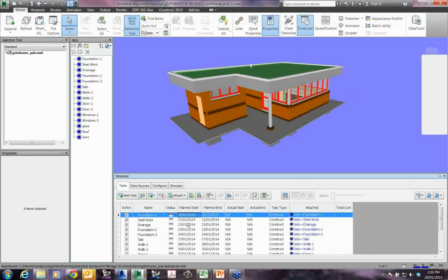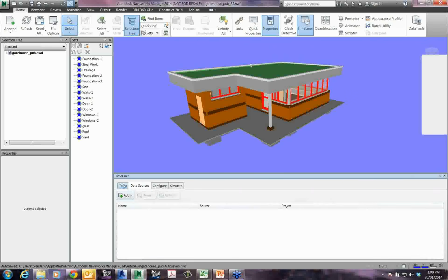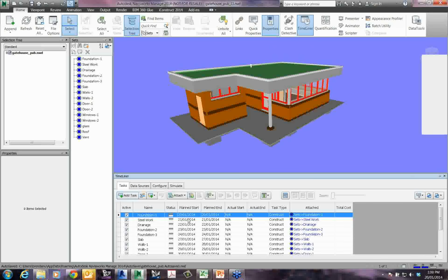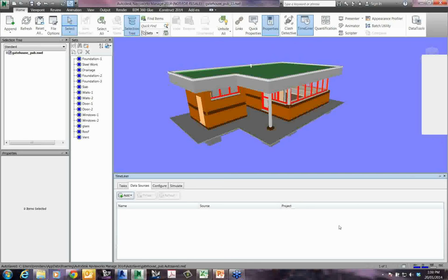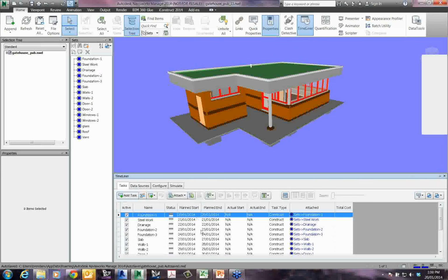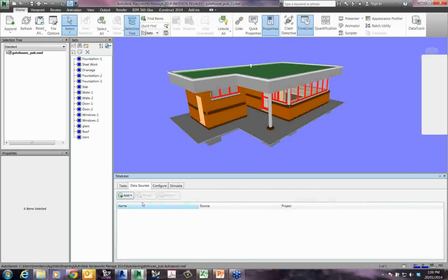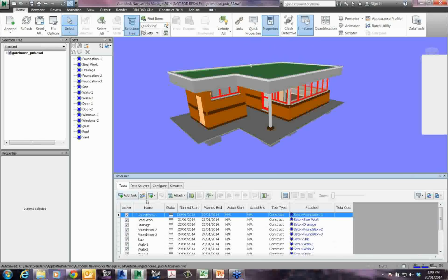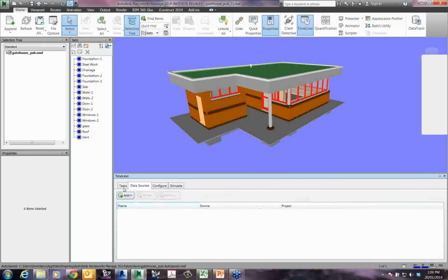Yeah, it's probably a good thing to note there as well, with updating the fields here. If you were doing this in the way that we showed at the beginning, by attaching a link to an external database, once you've built the task hierarchy from that link, from that external file, you can still go in and manually change the dates in there. But just keep in mind that if you do that, and then you later bring in a new link or update that link, and then you rebuild it, anything that you've manually overridden will be overridden by what you've got in the linked file. Okay, so just keep in mind that any manual updates you make whilst you've got a data link in there will potentially be overridden at some stage when that gets rebuilt from that link.